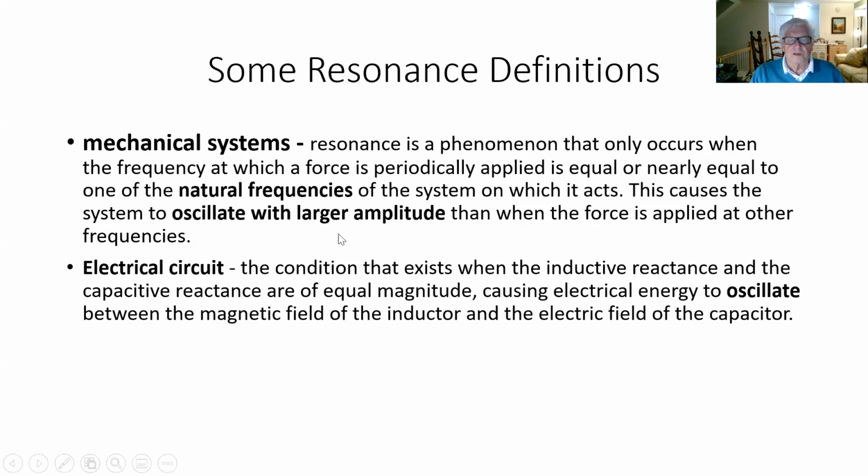Because of resonance, we can actually break something, because the amplitude of that frequency can build up and build up until it actually breaks the object. In the case of an electric circuit, though, resonance exists whenever the inductive reactance and the capacitive reactance are equal in magnitude. In other words, Xc is equal to XL.